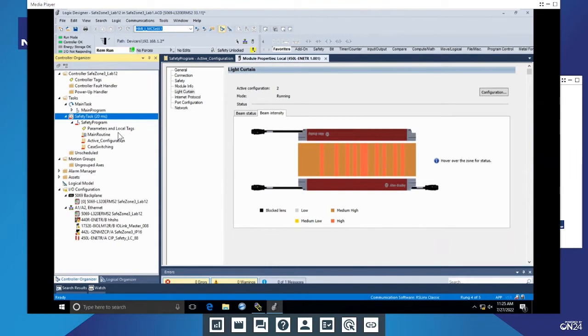PLCs and controllers on there, different types of I/O. What you don't want to have happen is one PLC telling your I/O to do something, whereas the other PLC hasn't. So ensuring that the I/O has an owner, in this case, which is tied into the safety network number, means that you can have these mixed devices on your network and not have to worry about who owns what, and you ensure basically that this I/O is only controlled by this controller, and that's it.